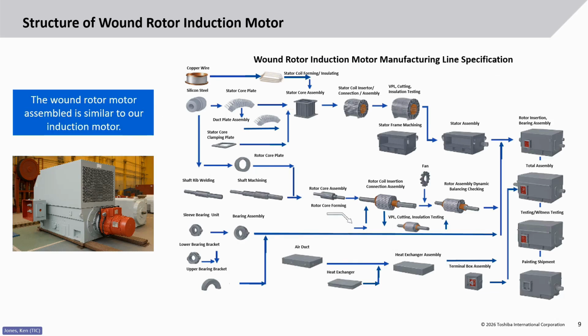This is typical for the assembly process for a wound rotor machine. Coil assemblies, because you draw so much more current through the rotor and rotor assembly, we typically use higher insulating patterns and materials in the rotor and rotor assembly to deal with that excess temperature and the current that's drawn across them. And so that's part of the design characteristics.